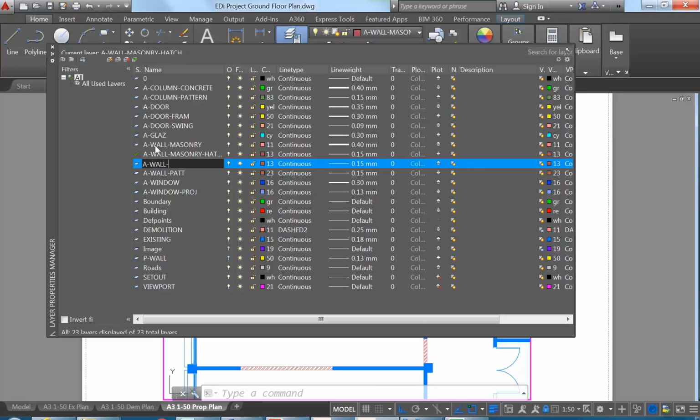Stud, did you say? Yeah, exactly, stud walls. Yep, that's exactly what I call them. Yep, so stud. You don't even need to nominate the framing type. It'd probably be steel for a building like this, but it could be timber, and they'd be plasterboard lined generally. But what would be the other option? Exactly. Yeah, AquaCheck or just fibre cement. Yeah, exactly. Spot on. So that's good.